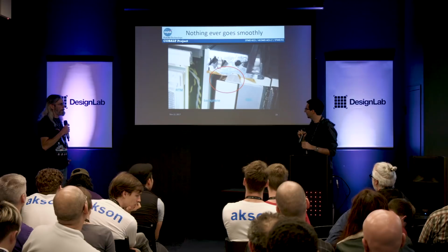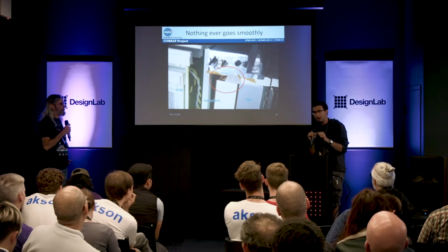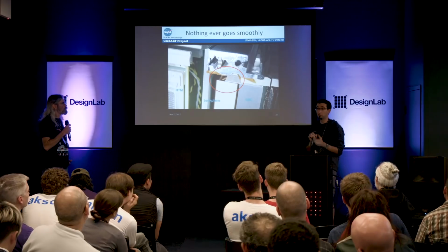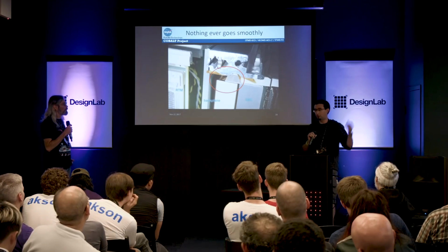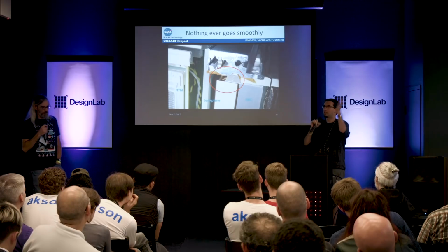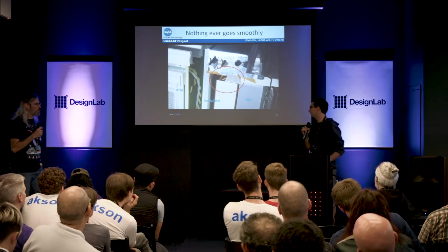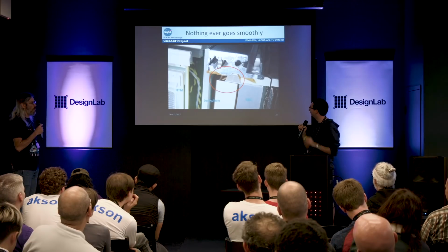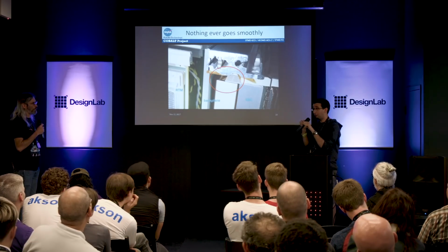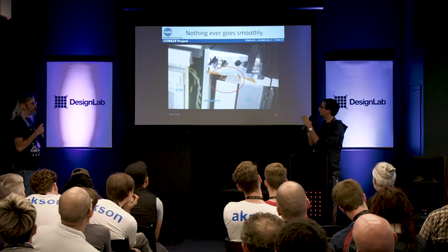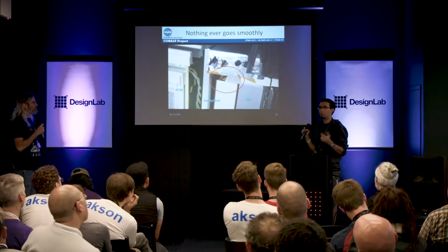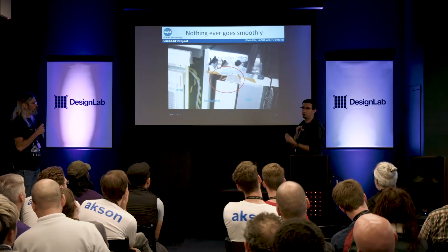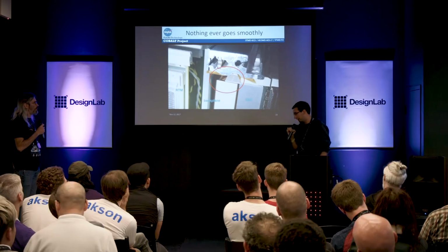So I tried to look at it. We thought it was power, maybe things are glitching here and there. We could not figure it out, and it was truly random. The temperature could be different, the alignment of the planets could be different or the same, and it didn't make a difference. It turns out the tolerances on our custom-made chassis were just wrong enough that these cards that slide in, which are a blind mate, we couldn't tell if they had made proper contact until we took it apart and realized, oh geez, the card wasn't seated right. So you push it in a little more, and suddenly your problem's gone away.